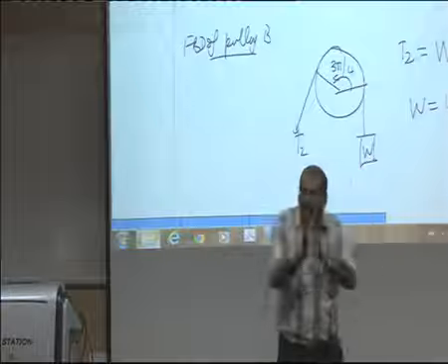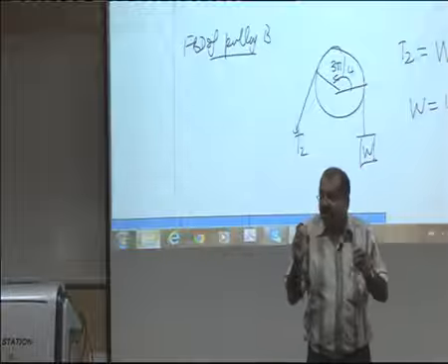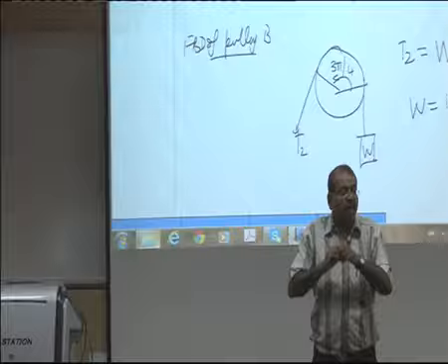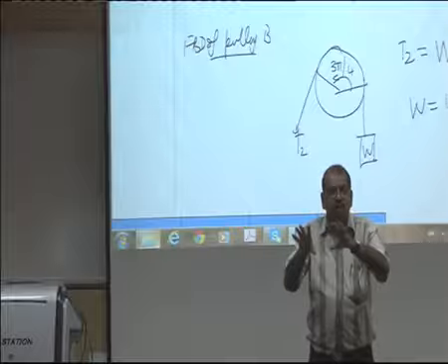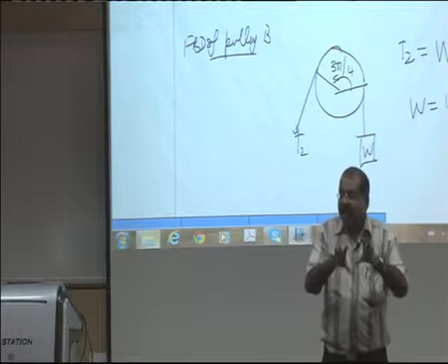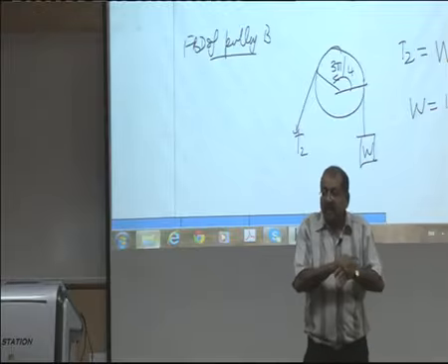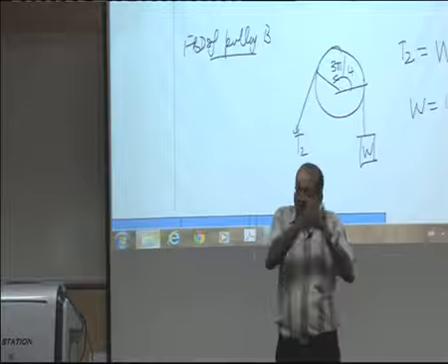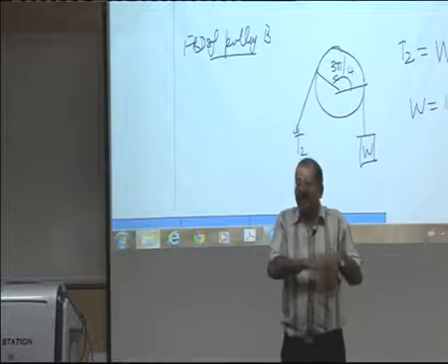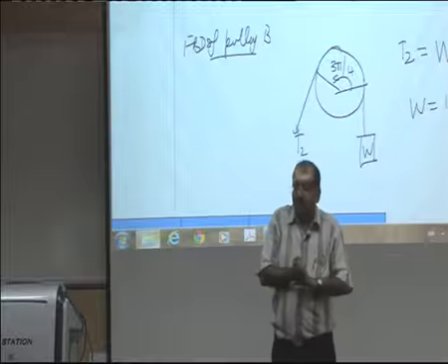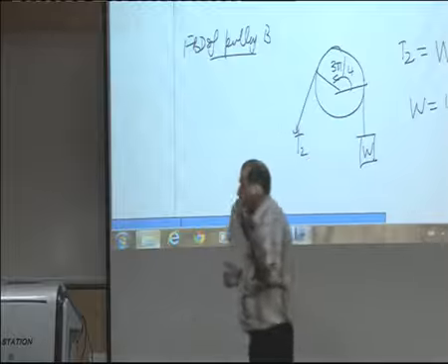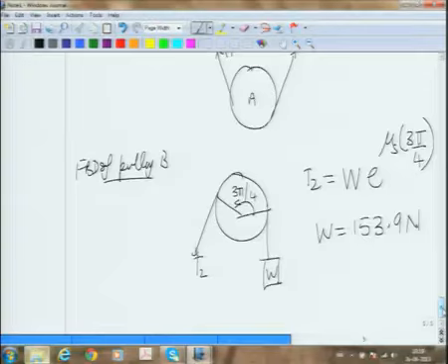In those problems you have to be careful: you apply a friction condition on one, and on the other you assume no slip. Once you solve the problem, you check that what you assumed is indeed correct. If not, that means slip is taking place on the surface where you assumed no slip, and you have to redo the problem. That is an important part of those types of problems.